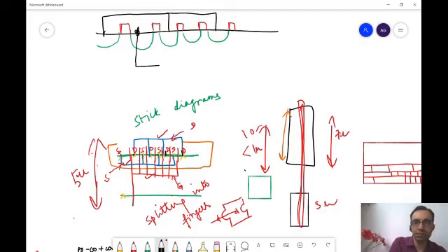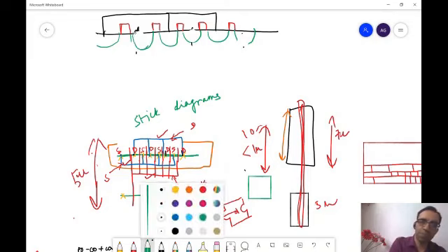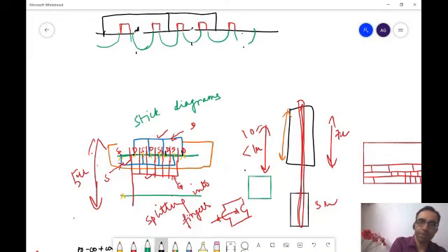And through another set of metals, you connected this, and this, and you would go here. So is there a way that source and drain would get shorted amongst each other? No, sir. So you just look at the cross section, it cannot happen. Source and drain are separated from each other through the depletion region. Okay, sir. Got it, sir. Thank you.